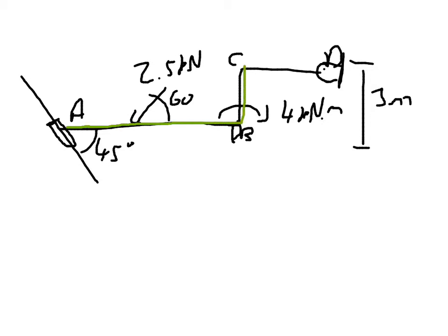And we're going to have to label some forces in this. So at point A, all we have to do is label reaction forces. Well, at point A, the sliding joint is free to move that way. So in that orientation there's nothing to resist the force, so there's no reaction force.